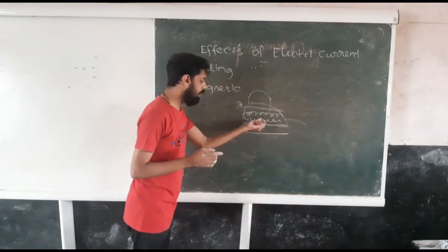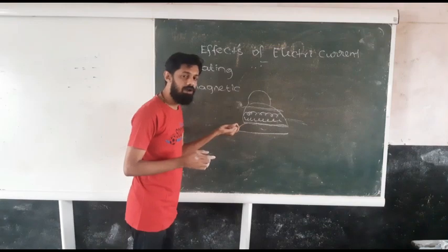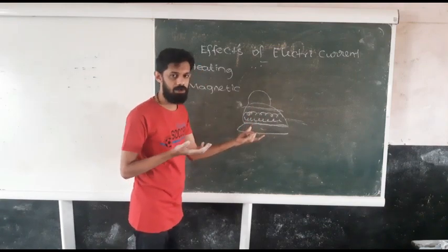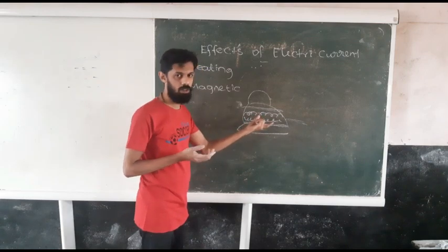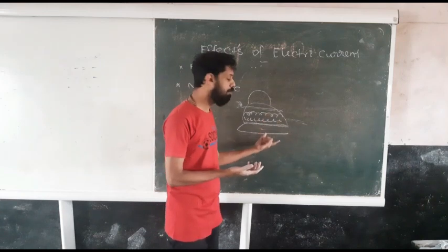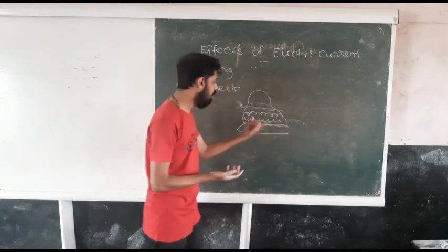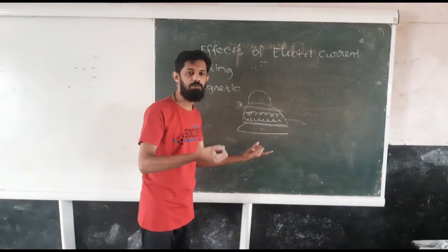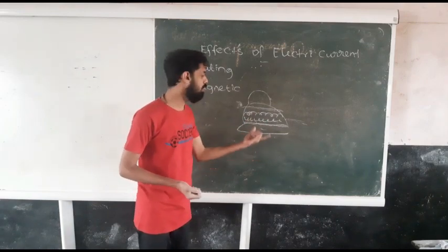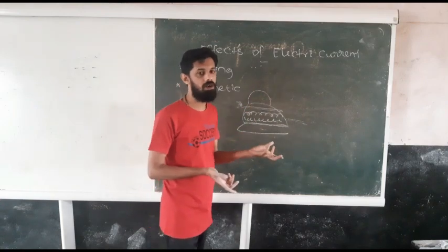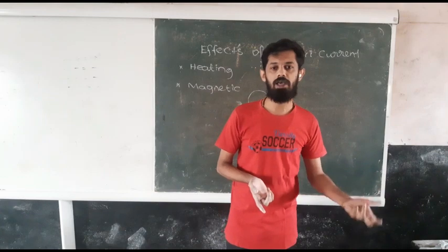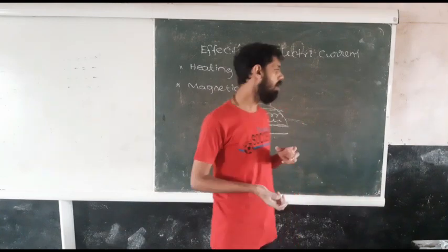When electric current is passing, the nichrome coil gets heated and passes that heat to the mica sheet below. That mica sheet helps us to iron our clothes, but it will not pass electricity, so we will not get any electric shock either. That's why we are using a mica sheet in the electric iron.